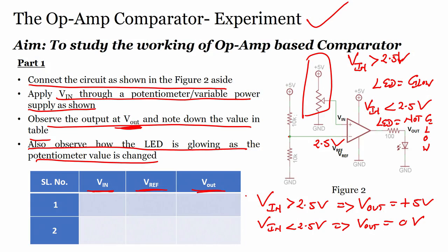In this case we have done the same thing and we could see how an op amp can be used as a comparator, and the LED was taken as an example to show that output is high and output is low, alright. So, let us move to the next module, and before we start the next module, what I feel is